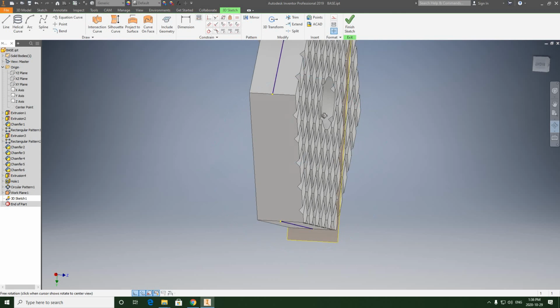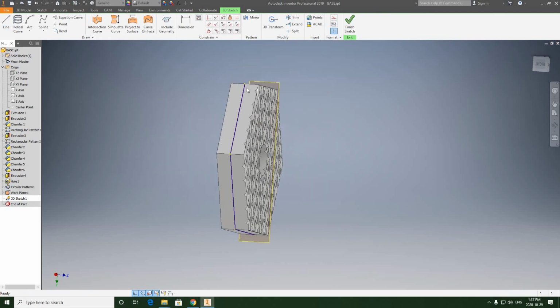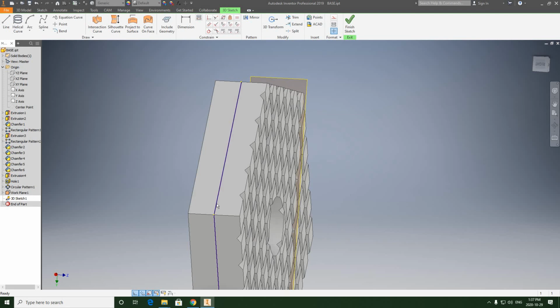And this is the last one. There. That is totally correct. So every time you snap to the second midpoint, you should read that 2.313, the length of your hexagonal side. All right.